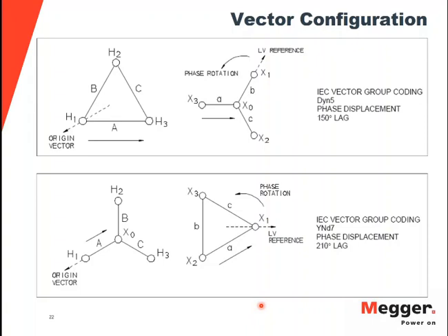So if you ever run into those kind of cases, you may want to use a three-phase source, as I said, or apply the voltage phase to phase, or try to energize from the secondary winding, or if you have a source that can apply 1000 volt and your winding can take 1000 volt, you may want to try to do those kind of things.